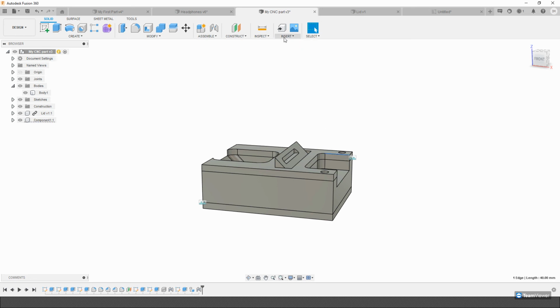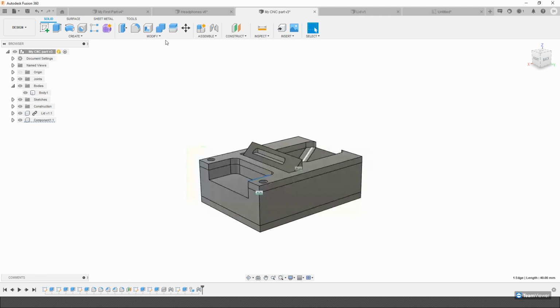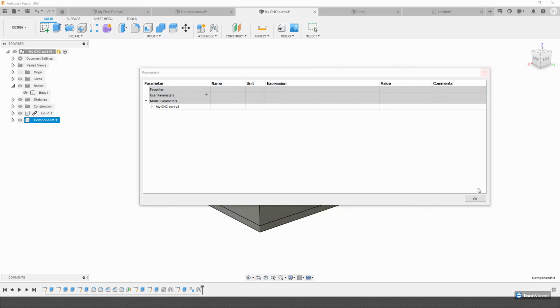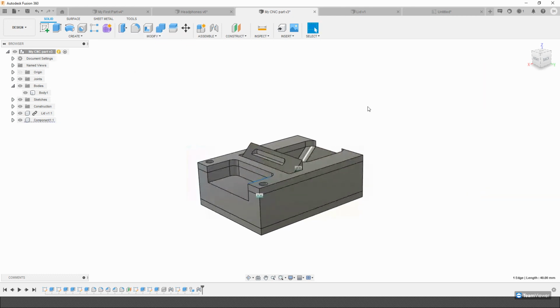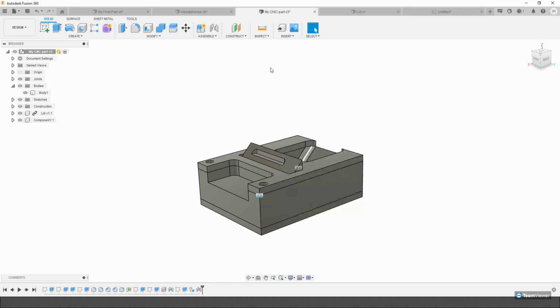When you were doing the parametric modeling earlier, is there a way to define parameters? So ones that are linked, say you want to link your width to your height. Yes, there is. There's the parameter window, which is almost exactly the same as Inventor. You can also, in the sketch environment, click on another dimension so that you link the two. Say you want your width and your length to be the same. Yes, you can quickly link it like that as well. But mostly I just control it from here, and if you give it a name and type in the same name, that usually links it up.